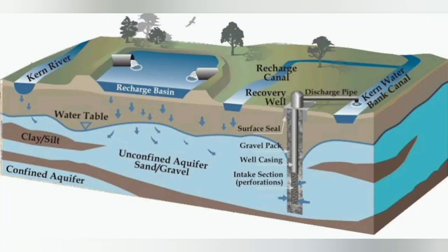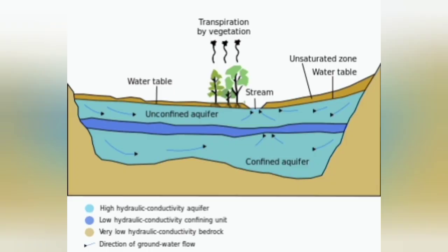So, when it comes to the geophysical studies, the main purpose of applying geophysical methods for the selection of an appropriate site for artificial recharge studies is mostly to help assess the unknown subsurface hydrogeological conditions economically, adequately and unambiguously. Generally, the prime task is to complement the exploratory program. Mostly it is employed to narrow down the target zone, pinpoint the probable site for the artificial recharge structure and its proper design.